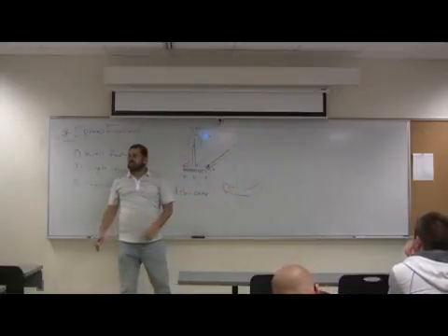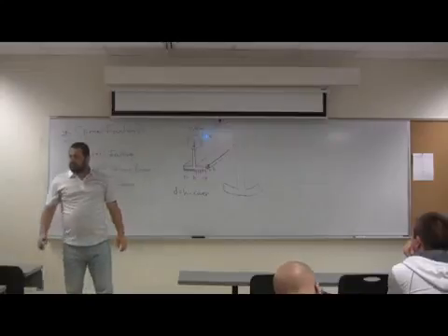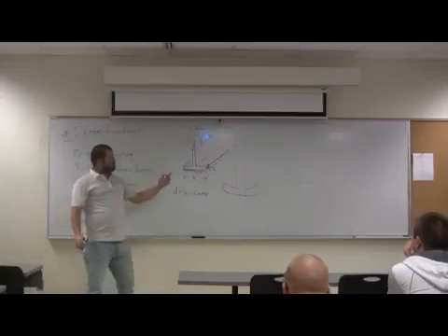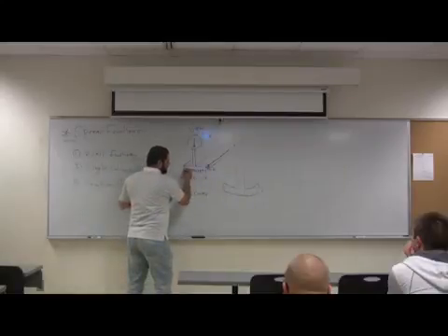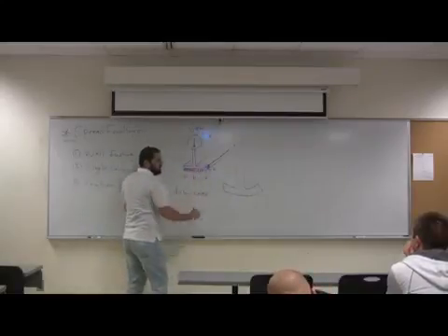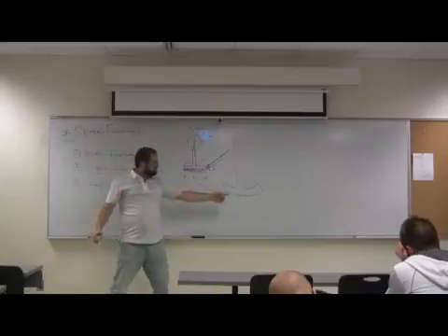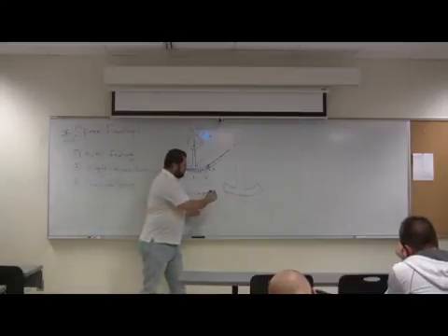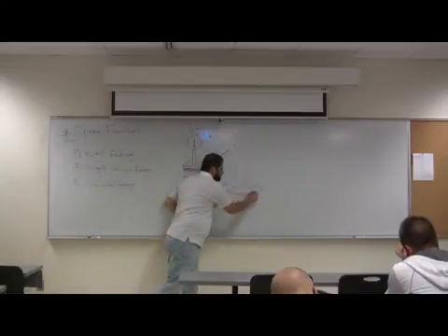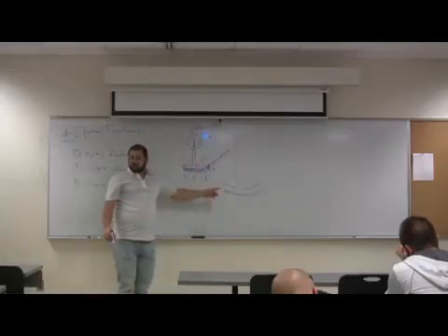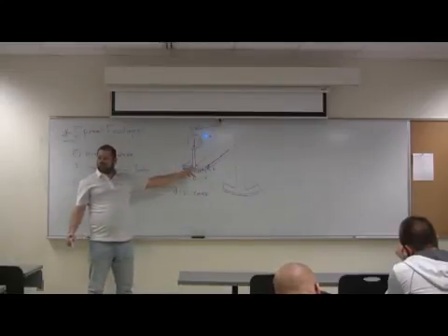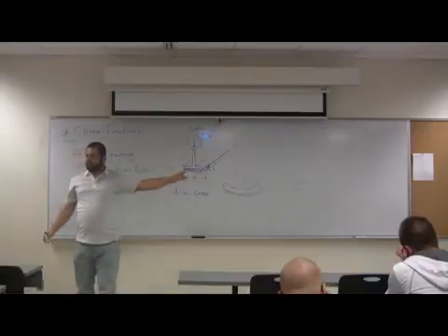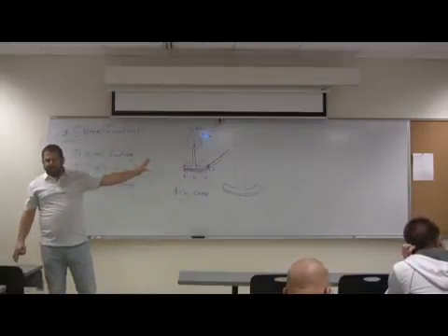So how is the reinforcement supposed to be? The main steel for bending, is it in the short direction? According to this, that's where the main steel is. And it's at the bottom, because tension is at the bottom. These are your bars here, and they have to be at the bottom. So we need to design for those based on bending. The reinforcement there is based on bending.